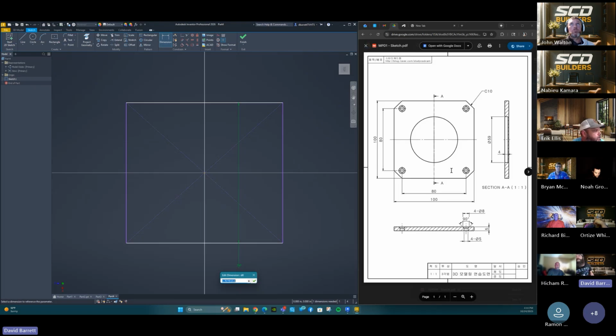On the page over here, it says on the outside diameter. How did you get that dimension edit? Once you bring it out, you click it one more time at the very end, and it brings up the edit dimension little tab. Now it's going to highlight it, so you can just start typing in what the dimension is.